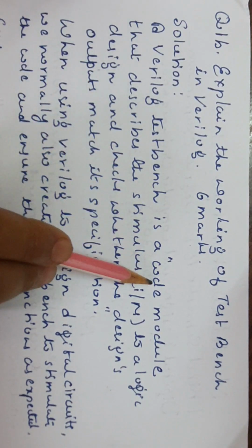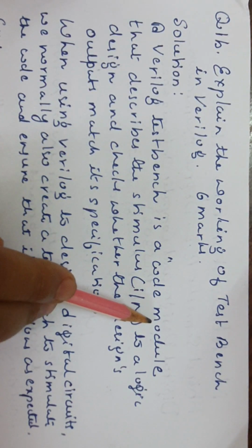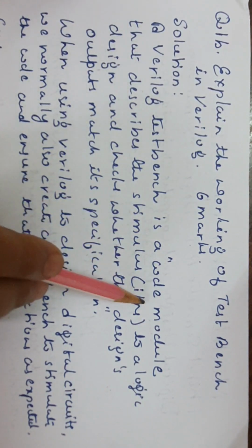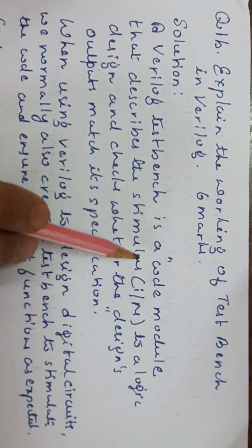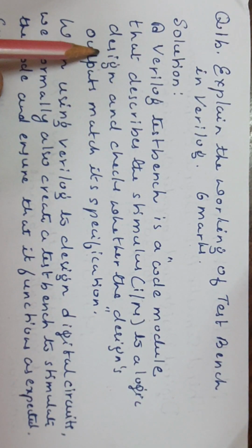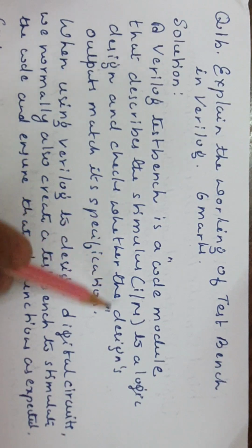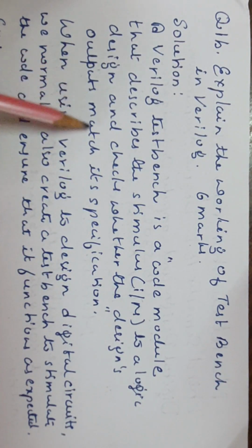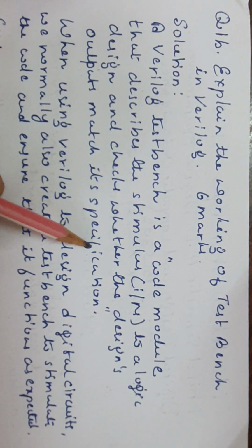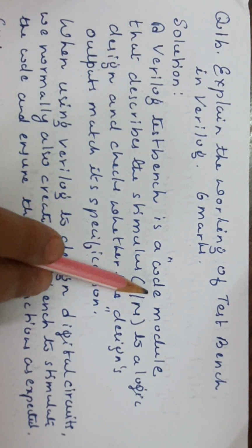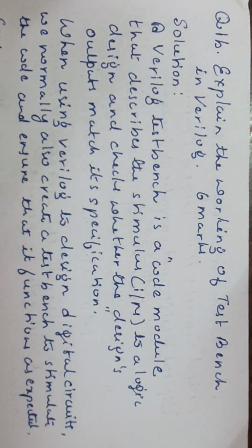For that, another code module or program is written in Verilog, which is called a test bench. This test bench program gives inputs to that program, means to the circuit in that program, and checks whether the design's outputs, means the output of that circuit, match its specification, means whether it is behaving according to the requirements for which it is designed, yes or no. So that code module is called a test bench.